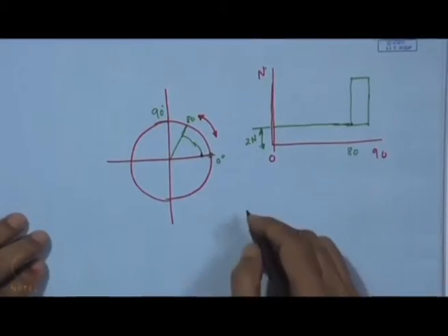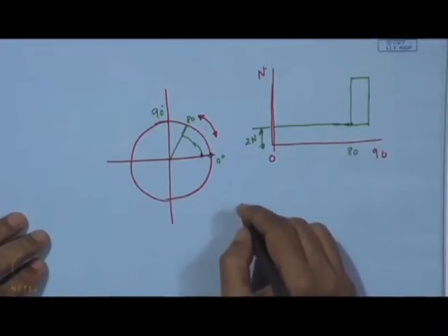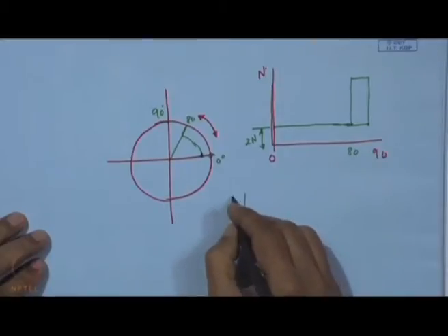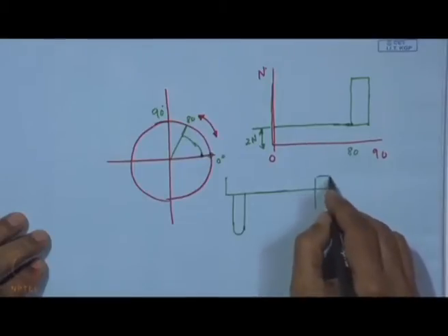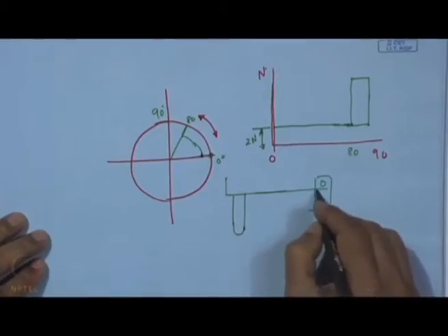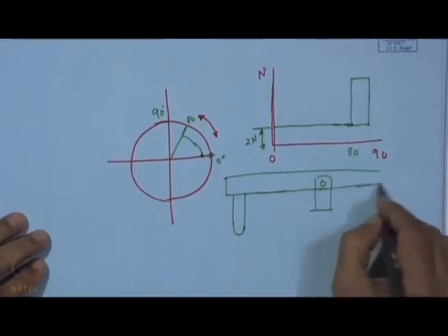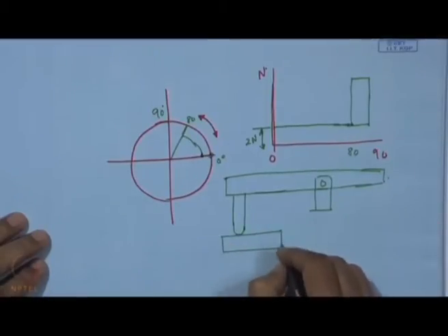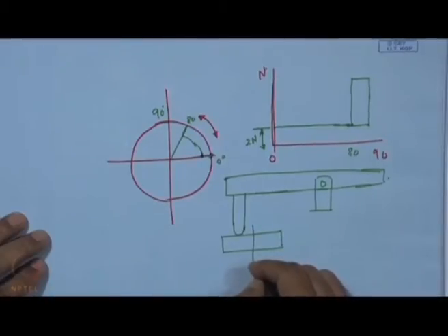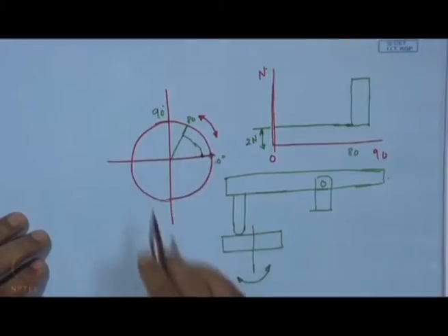case what we can see that in this tribometer, this is the pin, and then we have this arm, horizontal arm, this is the pivotal point, and that is the extension of the arm, and here say we have the disc which is actually oscillating. So, this is actually oscillating over say 90 degree as we have shown here.